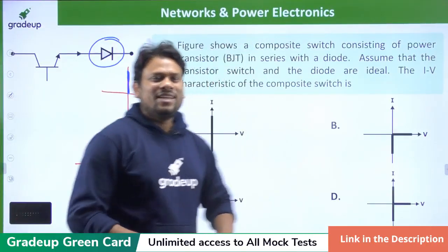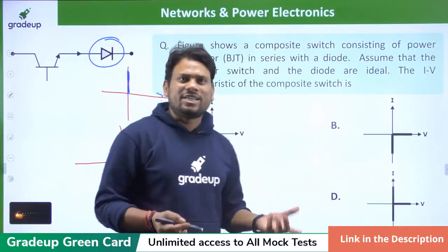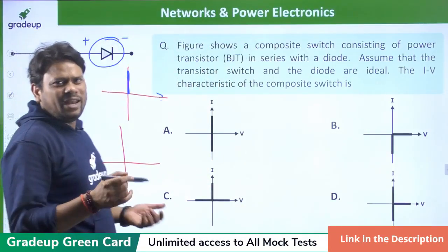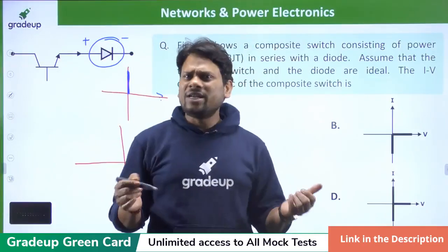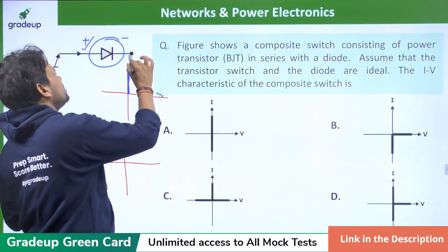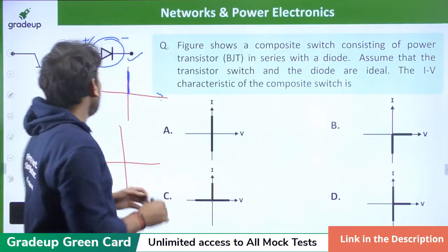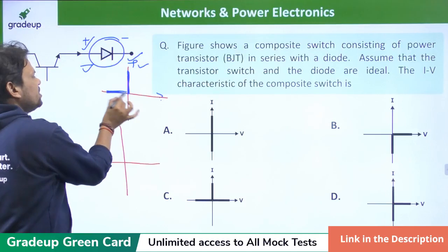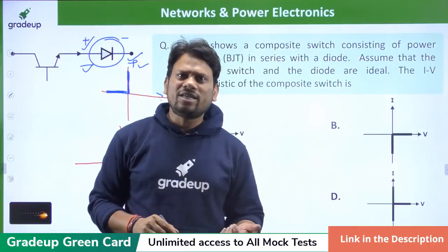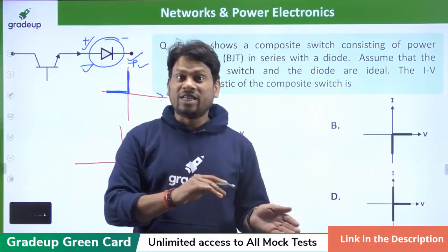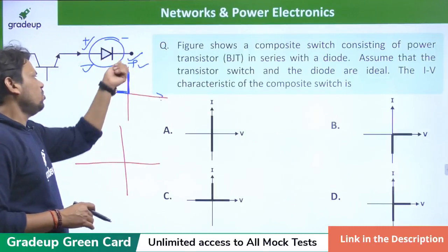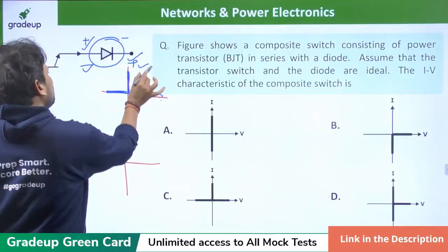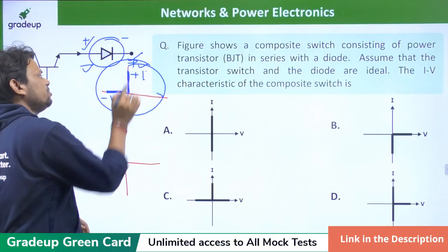Okay, good evening Prathavan. Now see, when the diode is off, it can block negative voltage only. You know very well, if we apply positive voltage across the diode, suppose here positive, here negative, an ideal diode will conduct definitely. Nobody can stop the conduction of the diode when the anode voltage is just greater than the cathode voltage. Now if we apply negative voltage across it, it will be off and it will block whatever voltage we apply across the diode. So the diode can block negative voltage. On that basis, we can say it is a unipolar device with respect to blocking voltage. Please mind it, okay? And with respect to positive current passing, it is called unidirectional, because current flows only from anode to cathode. So this is the VI characteristic of the diode, where this is minus V, and that one is plus I.